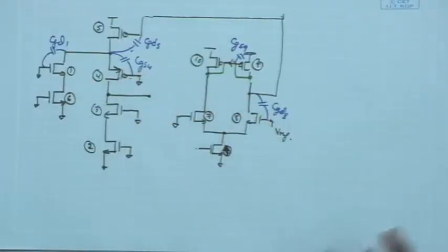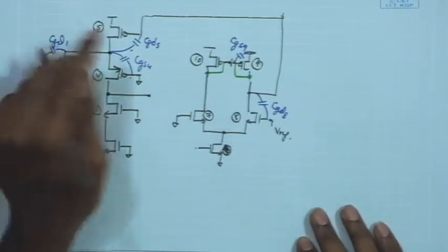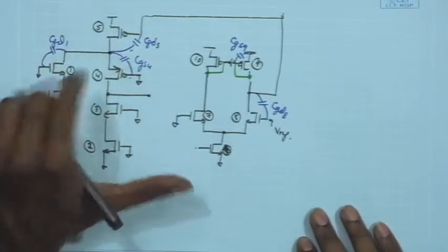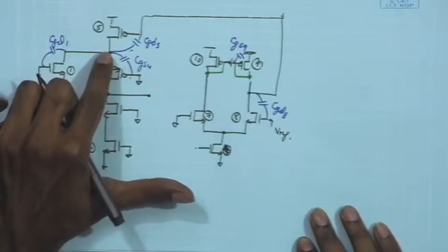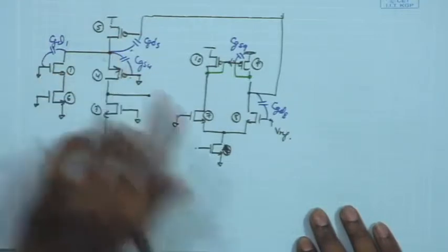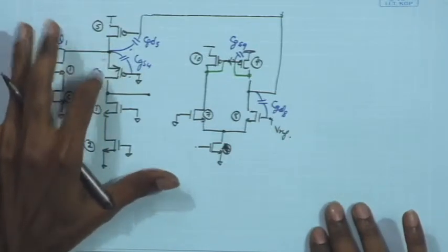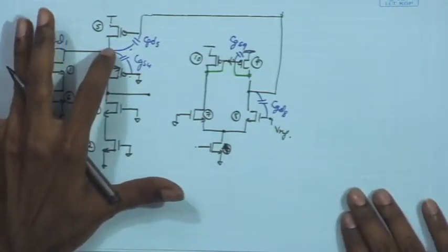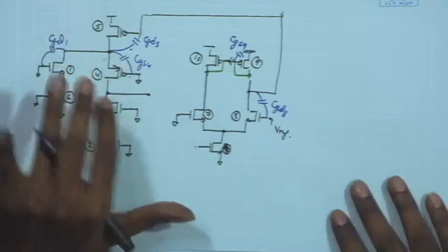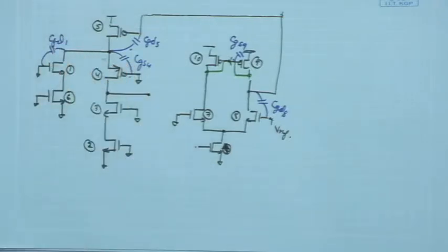Welcome back, and let us resume our discussion on the stability analysis for the common mode feedback loop for our cascode amplifier. We are looking into the parasitic capacitances that are going to determine the overall capacitance at the non-dominant pole, and we are looking at the condition where we make the dominant pole at the output gmro times the non-dominant pole, so that a good phase margin close to 45 degrees can be achieved.